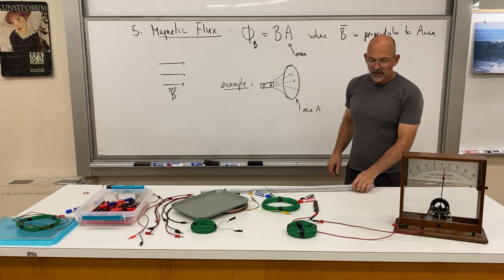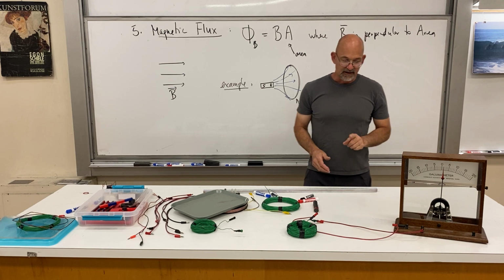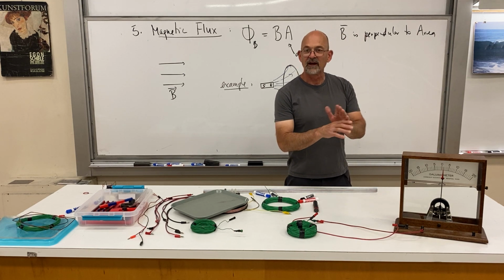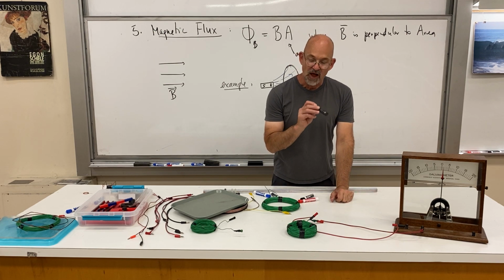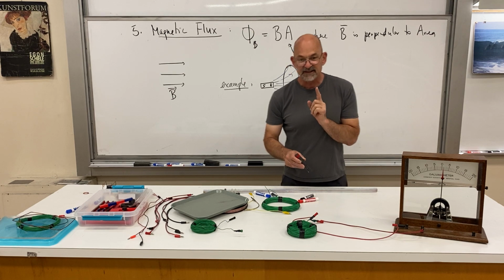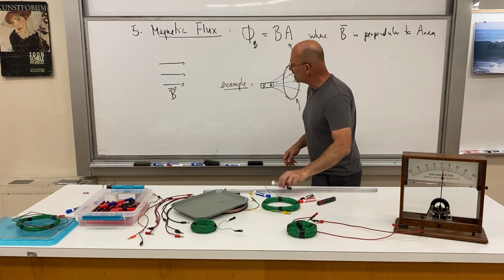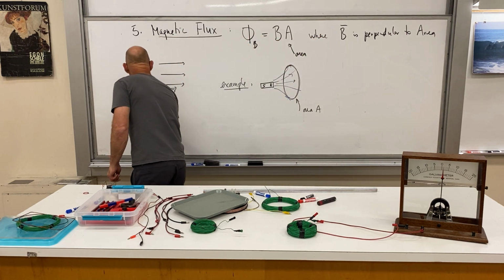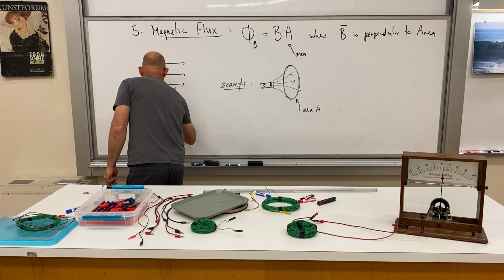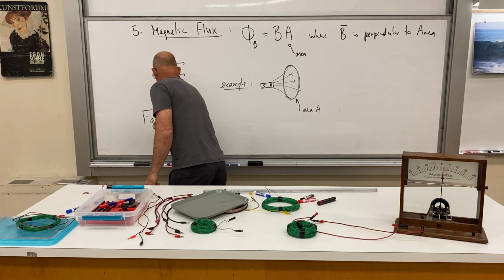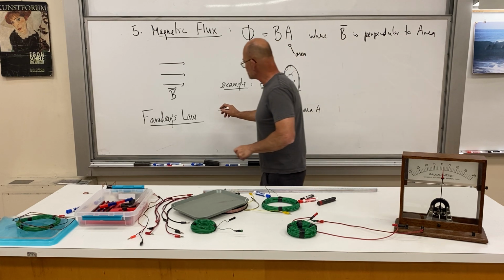So there's a law here about what creates an electric current. And in fact, what creates an electric current is an electric voltage. And what creates the voltage is the change in flux, okay? So it's not the flux itself, but it's the change in flux. I'm gonna write this down as our fifth law. And this is so famous, Faraday's law. And then I'll demonstrate it a little bit more. A changing magnetic flux produces a changing voltage.